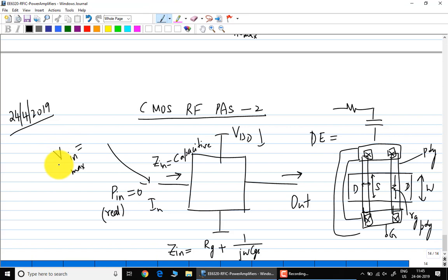Okay, in a general PA, if you already know the power gain and the output power, you can calculate the input power. Okay, for a CMOS PA, I don't know what the power gain is, because I have so far been assuming that the power gain is infinite for the CMOS PA. So I'll start off with V out max, which I already know as a part of design, over the gain. Does it make sense? Where gain is just the AC gain while driving RL. Now, based on this V in, I can calculate P in.